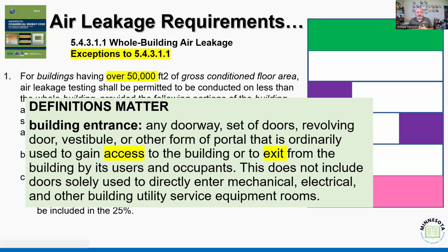Now, this is one of those moments where I'm glad I don't represent any of the jurisdictions in Minnesota. But generally, what I look at is the term "ordinarily used" does not, in my experience, when I've had projects use this, include those egress doors that don't get used regularly, those emergency fire egress paths, right? And so again, if this is something that's used to generally access and exit a building, that's what I'm considering a floor that needs to be tested.